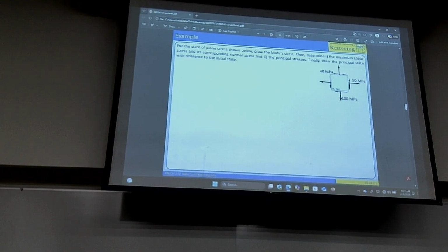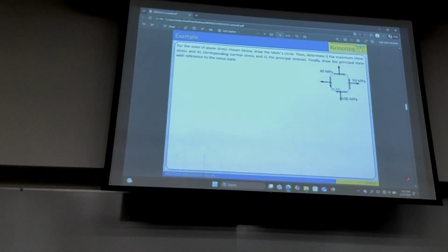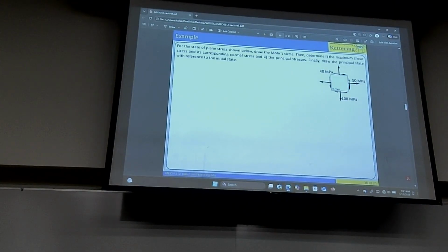You want the sigma x prime equation. I think I have it. Is it? Say it is. Believe in yourself. You're looking at your own handwriting. It is sigma x prime equals sigma average plus sigma x minus sigma y over 2 cosine 2 theta plus tau xy sine 2 theta. Guess what? If you were asking, and then if I said yes, then you would have to repeat all of that. But you said it is, that's correct.